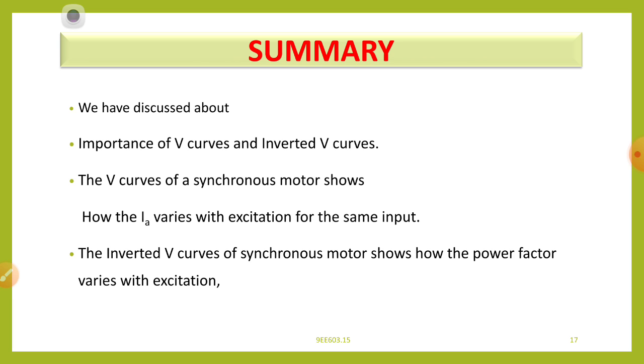This reactive power consumption and generation affects the power factor of the factory. So we are required to maintain the power factor at 0.85 lag, or sometimes unity power factor, to avoid excess current from the supply, as well as to operate our motors up to their full rated values.